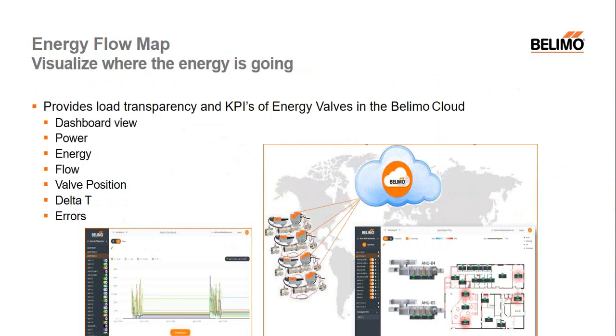So, in the first floor, second floor, etc. The building managers and energy managers, how they would utilize this, that I've talked to, is they would get the valves installed, load their flow map, and they would map the valves according to the flow map, and they would look at where the largest loads are first. And that's the areas that they would concentrate on first. Is there additional opportunity in these areas for more optimization?